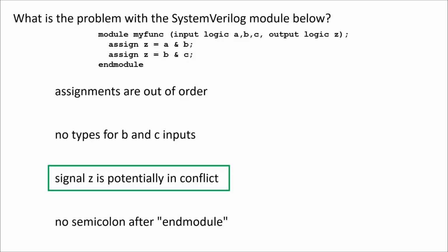So that's Z. And then there's a fourth value you can assign to a logic signal called X, which is used for several things in Verilog. It's a don't care, it's a contention, it's an unknown. It's kind of like the other case. If the simulator doesn't know what it is, it's X. Does that make sense? So it's 4-state logic. Instead of binary, there are actually 4 states. It's like a quaternary value.